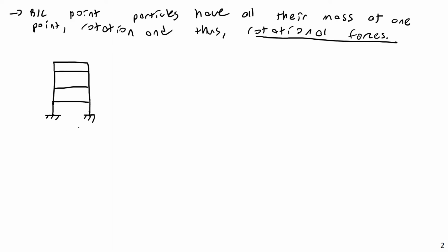Again, this is not a course on seismic design, but one of the major aspects of seismic design is something called overturning moment. If the ground suddenly moves rapidly this way, the building is going to have a tendency to rotate over like this. You actually have a rotational force, not just a lateral force, but a torque, a rotational moment that tends to cause this building to fall over, not collapse downward and not snap at its base in shear, but actually overturn.